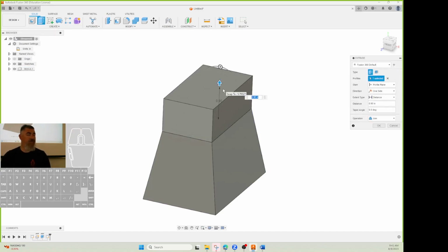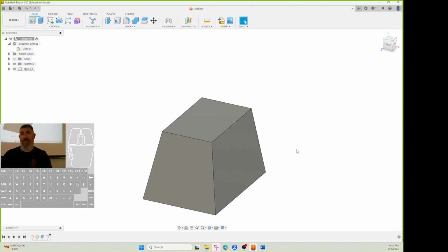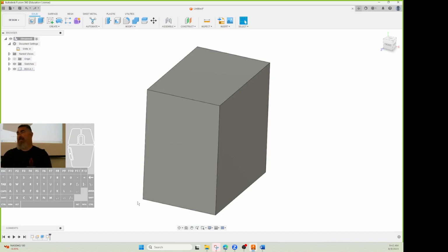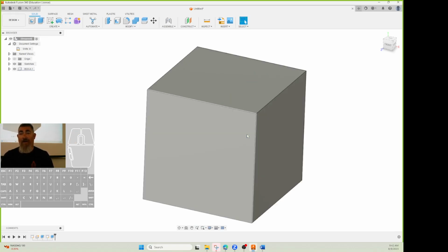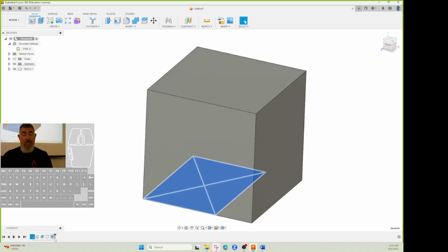And make it a new extrude. But don't just do that to add on, make it bigger or smaller. Go back and edit the original sketch or whatever the feature is. Don't be like, oh, I need to make it another inch. Ta-da! No, don't do that. Because now you want to change the width, you have to change it here or here. It's not right. Do the one thing.